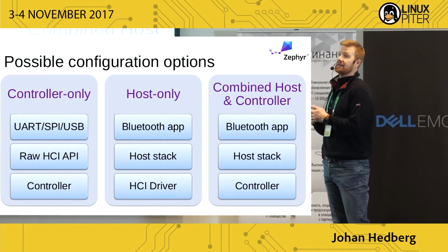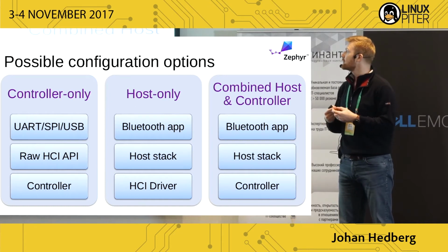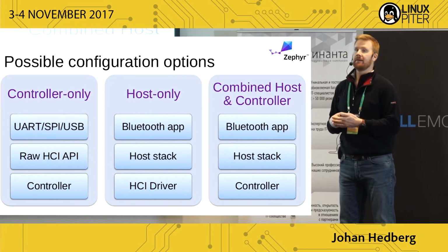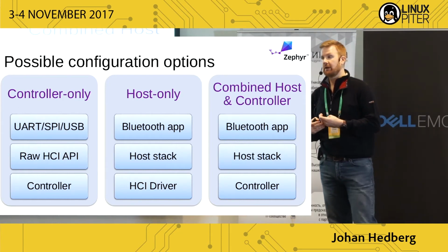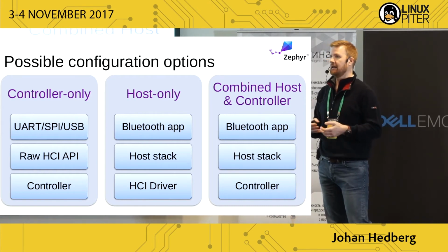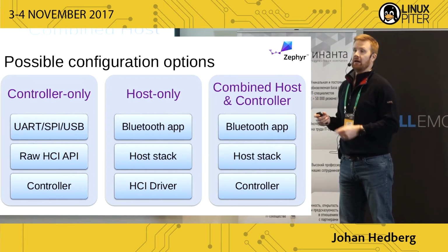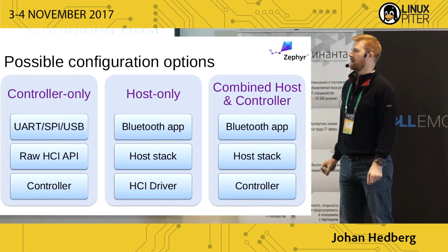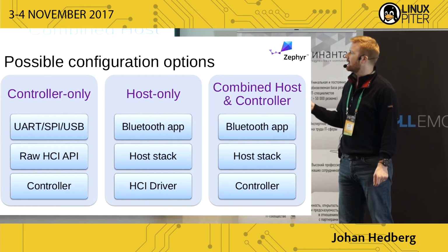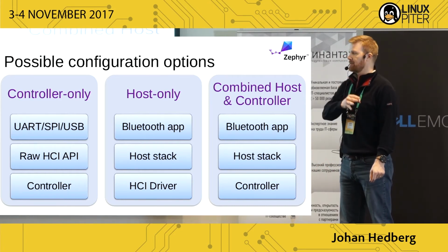And you can actually build Zephyr in different configurations depending on what you want to do with the Bluetooth controller and the Bluetooth host. So you could have your controller only build. This could be useful, for example, if you want to use your Linux PC BlueZ as the Bluetooth host stack, and then have Zephyr running on the controller. Nordic has these nice small nRF51 USB dongles that you can put just the Zephyr on and plug into your laptop and use it then from the laptop's host OS.